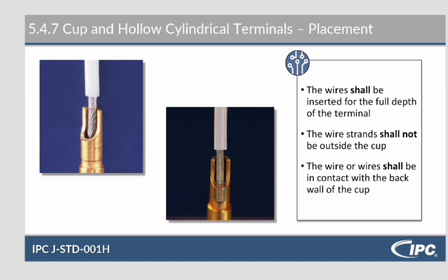Cup and hollow cylindrical terminals. The wires shall be inserted for the full depth of the terminal, shall not be outside the cup, and the wires shall be in contact with the back wall of the cup.